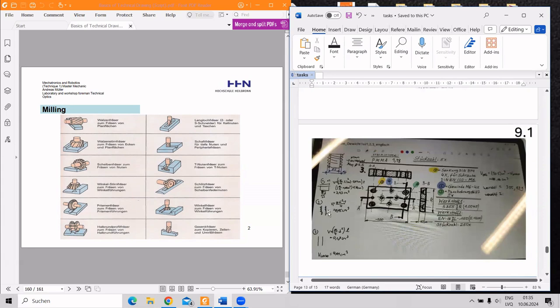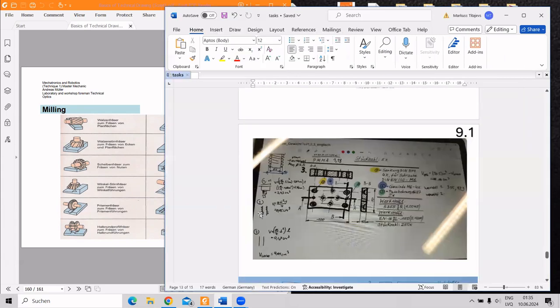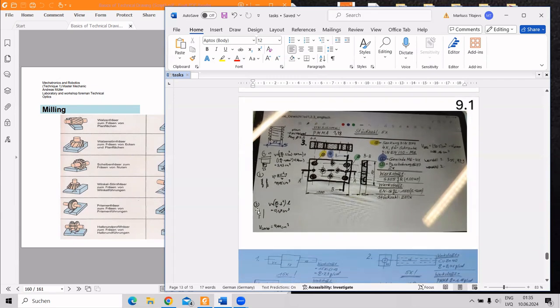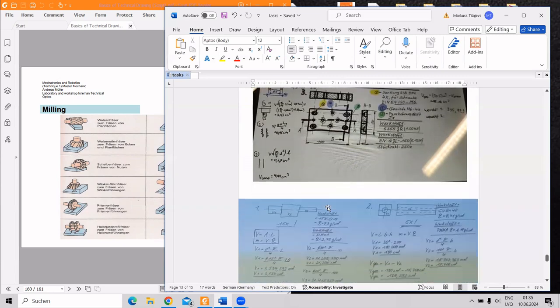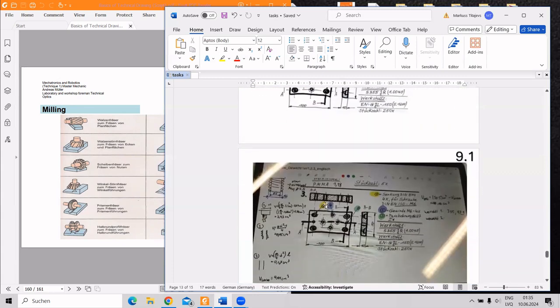So here I have just a sketch that for a thread, a screw, we usually need to calculate the middle value. So if the outer part is, for instance, 6 and inner 5, we will take the middle value 5.5 as a diameter. And we need to calculate the screw head part of this additionally. So we take the measurements from a table book. So usually it's a cylinder, and if it's just a hole, we take it as it's given. For instance, M6, we take 6 millimeters diameter. So it's one of the important nuances here.